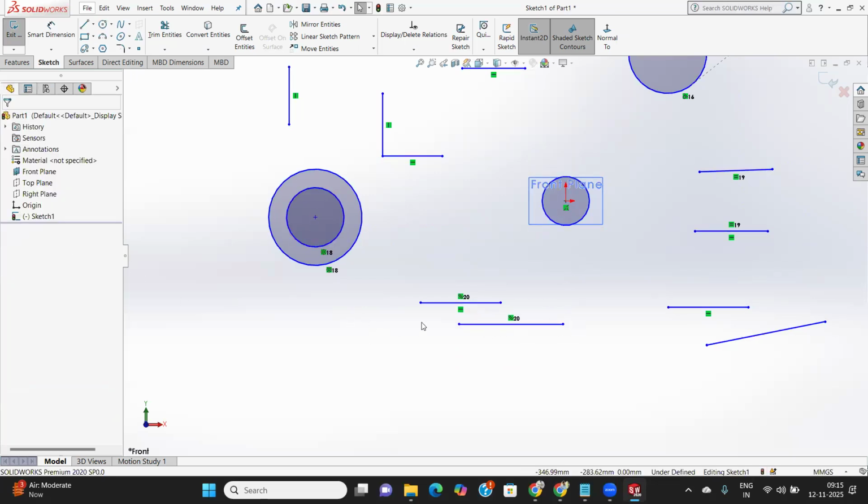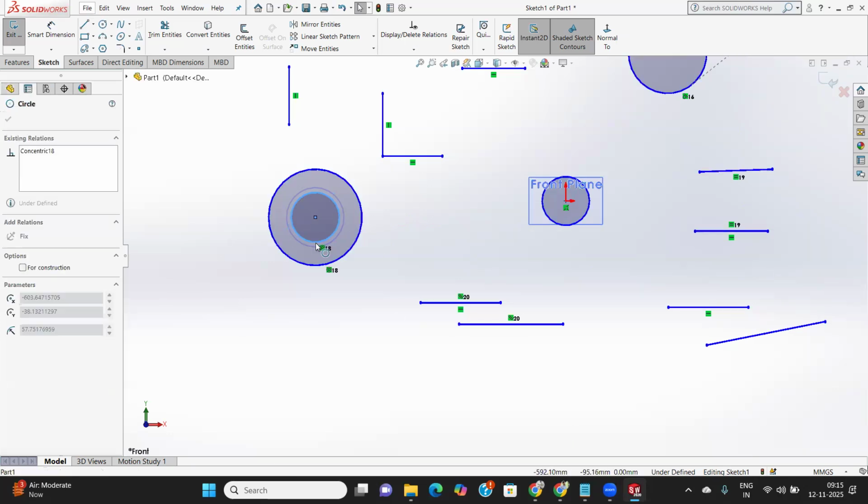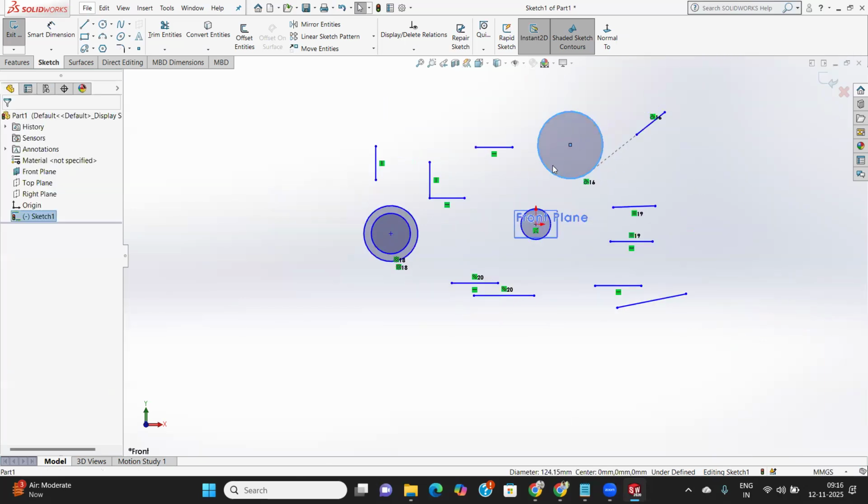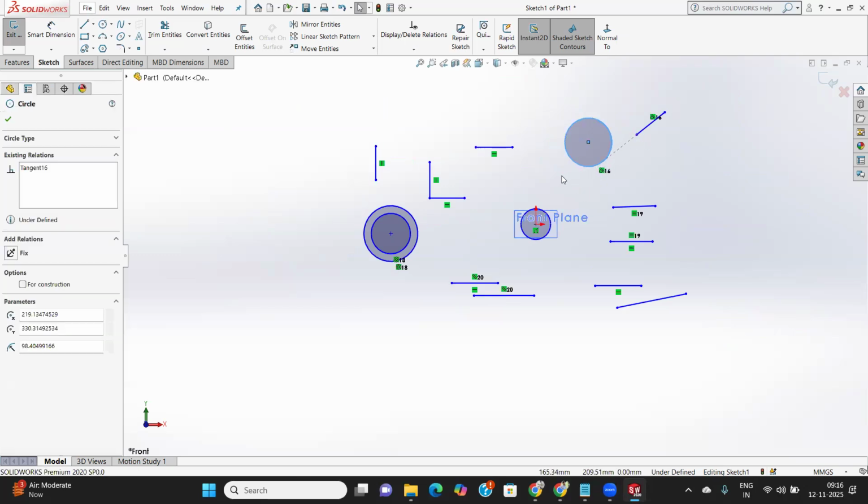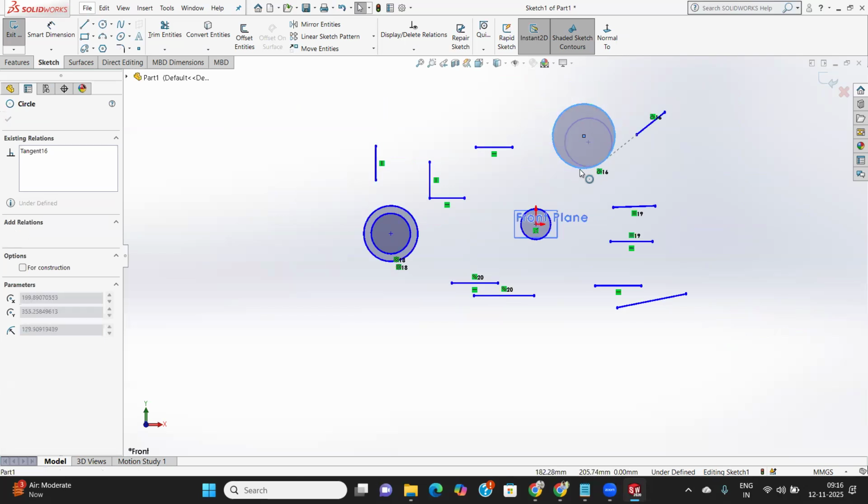If you apply a geometrical constraint, the fixed function is right here. If I move this small circle, this circle can't be moved but can be scaled, because it has a fixed center point. And this circle I also can't move, because it is fixed. But this circle I can move, because it is not fixed. But this line will be shown in a tangent position, so every time you show it here, it will make a tangent.